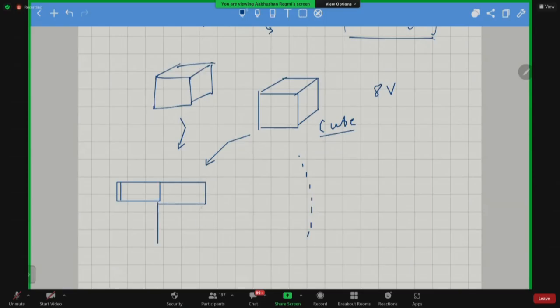I'm just giving the top view of that geometry, something like this. And then I want another block over here, and another block over here. From this side, I'll say that there is an inlet. From this side, I just want an outlet. And I want to simulate this sort of a flow. But you know that this is going to be a cumbersome process to write in your blockMesh dictionary. So the way I work around this is I put all of these blocks into Blender.